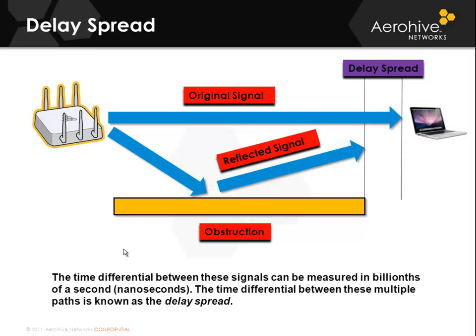But unlike 802.11n's use of MIMO, SISO devices strictly use this for diversity. Whichever antenna receives a stronger signal, that signal will be believed, and the other signal will be discarded. The signal usually arrives via multiple paths and with different angles of arrival. The time difference between the arrival of the first multipath component, which is normally the line of sight component, and the last one is called the delay spread.